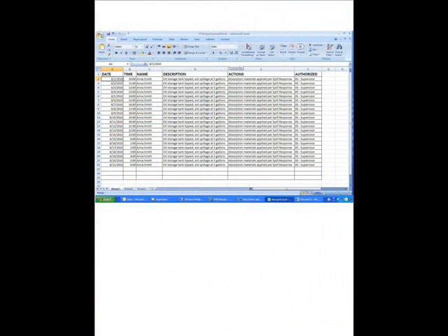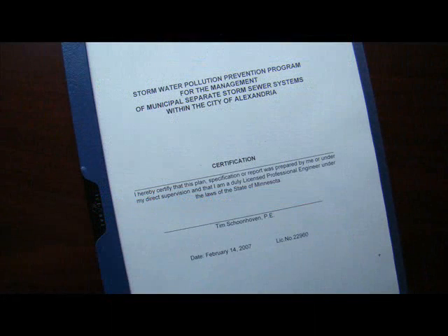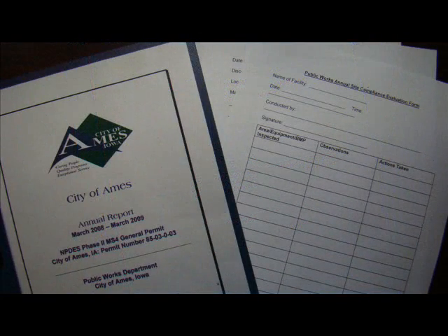It is recommended that inspection information from hard copy inspection forms be entered into a spreadsheet type tracking form. This will provide an easy summary of historical inspections and responses, including new best management practices. It may be necessary to update stormwater pollution prevention plans that may be available for each site along with spill response plans. Note the amount of time it took to conduct the inspection at each facility and use this information to add to your list of stormwater program expenses in your annual report to the Iowa Department of Natural Resources.